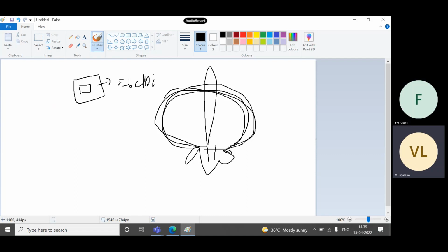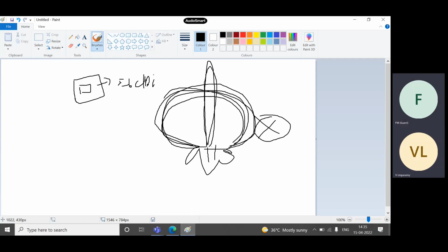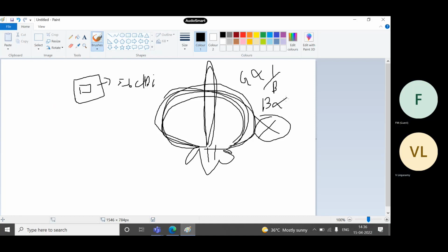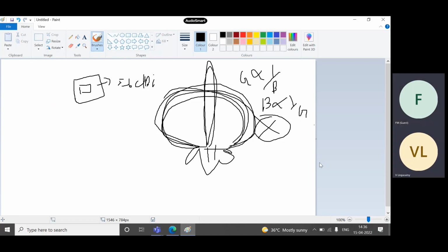But if you are focusing the same energy, for example, some X power is distributed among this whole direction, and now we focus the same X amount of power in a particular direction with high gain, then the gain will be higher. So there are three parameters here. Gain is inversely proportional to beam width, or beam width is inversely proportional to gain. Whenever gain increases, the beam width narrows down. It is a similar analogy.